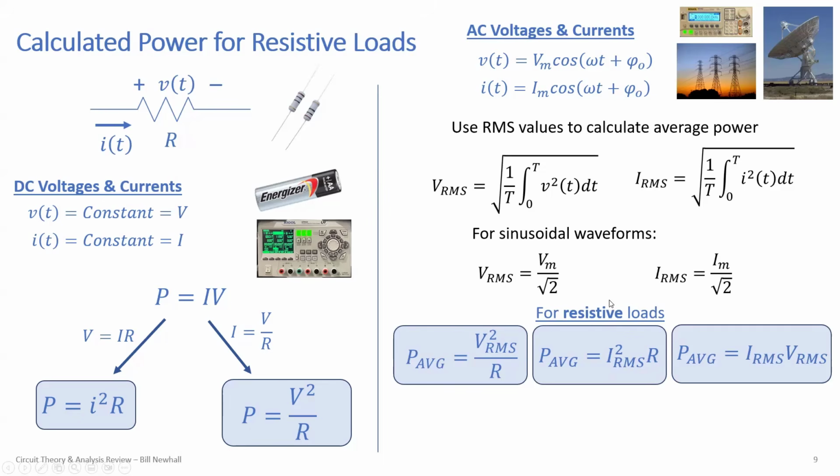So if you want to calculate the power radiated from a highly efficient antenna, you could use this. You could say, I know the peak value of voltage across the terminals of the antenna, and I know it's a 50 ohm antenna. You can calculate the power radiated. So there's a lot of use here in just Ohm's law and power calculations for components beyond just resistors.